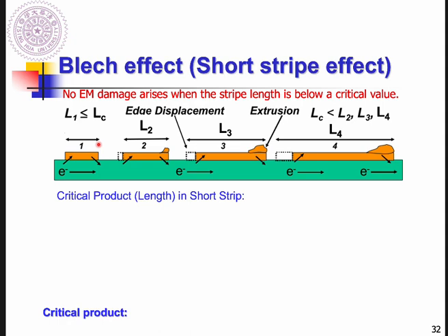Okay, so in order to answer these questions, probably you need to write down the atomic flux, and how many possible driving forces act to induce this atomic flux. If you analyze this conducting line, how many driving forces act on it, because there are electrons flowing through this material. So the first thing that comes to mind will be, Professor, EM. So yes, the atomic flux for sure will be driven by the electrical field you apply on this material system. So it will be mobility, concentration, and driving force beta E.